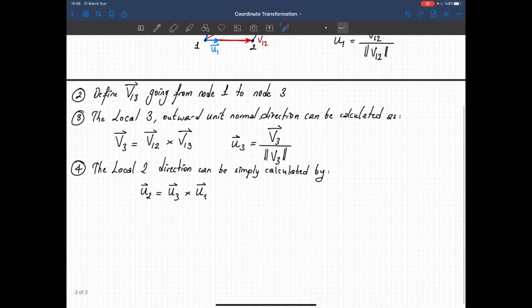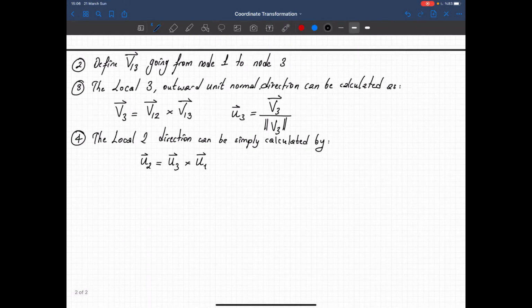So that's why we have the second approach, which uses the coordinates of 4 nodes, and we will be using this approach when we have a warped shell element. And if you want to model the warp geometry by using the flat elements, this is the approach that you will use. So let's put it as a note.